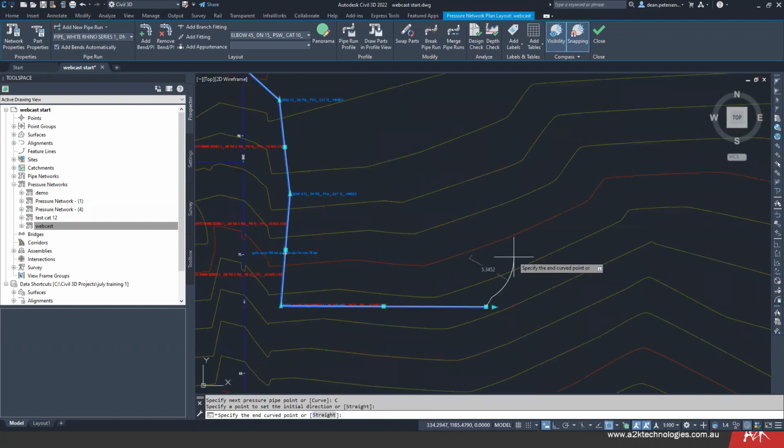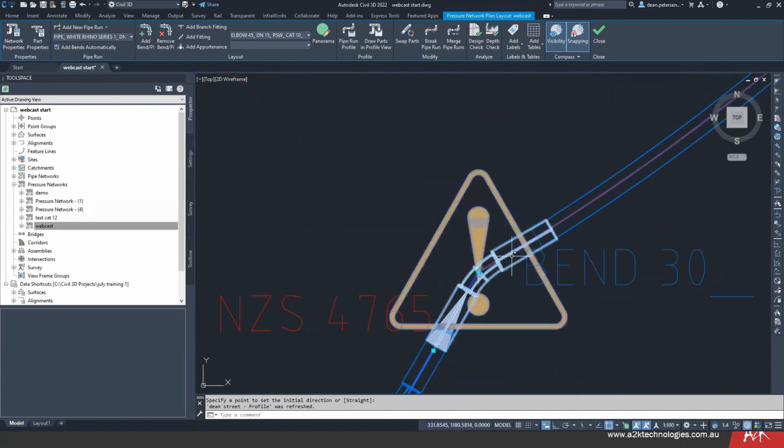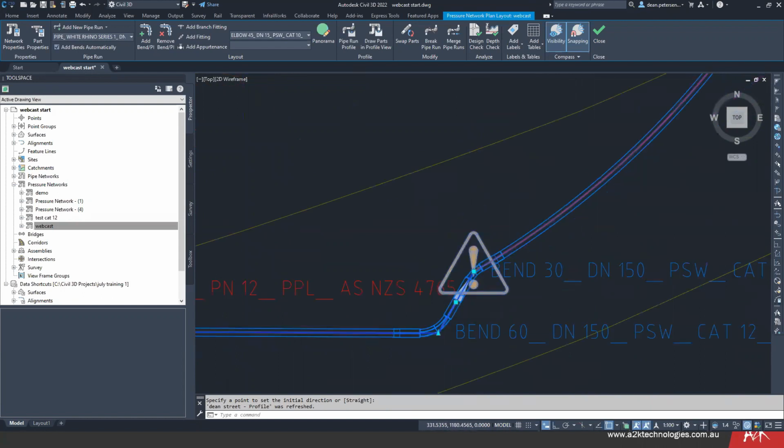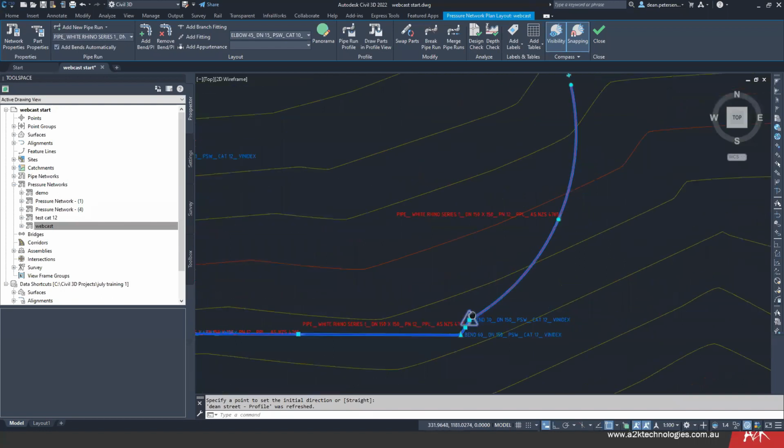Sorry, an angle of that much, and then it'll make a curved pipe. And you can work out where you want your end point to be. Click again, enter, and that's just added that onto that. Although it's broken tangency at the alignment here, which is just the alignment label, not to do with the pipes. So you can do curved pipes there.